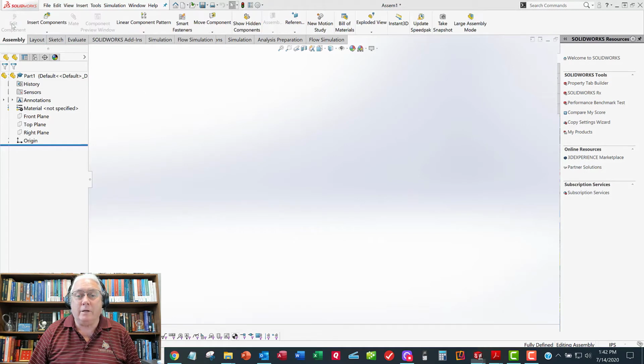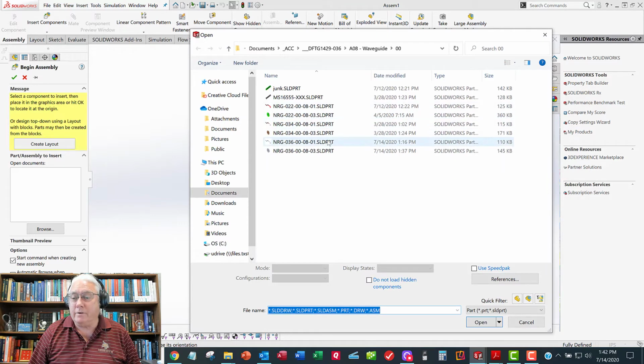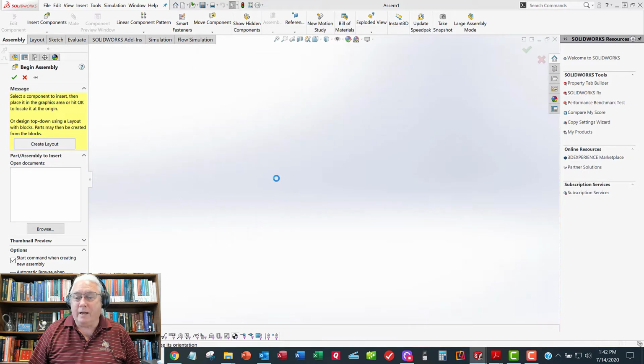Alright, so now we're ready to place components. It does that by default. You notice our part numbers. Don't forget to use our ZZ. There's your student ID, there's the assignment number, and there's ZZ, our unique identifier. So we don't have any mirror image parts, so we're using -1, -3, -5 on down the line like we do with the RF load tray. So I got -1 is the waveguide, -3 is the flange.